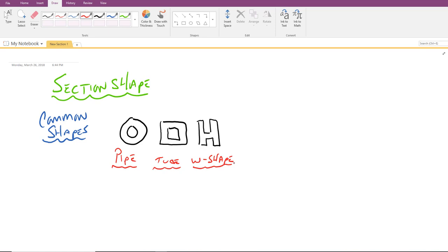And the easiest way to do that and provide some shape stiffness is to push the material away from the neutral axis. So you'll see those two major features in all of these three shapes. Basically the same in the weak and the strong axis, the same dimension, and essentially pushing the material away from the neutral axis to maximize the material that's there.